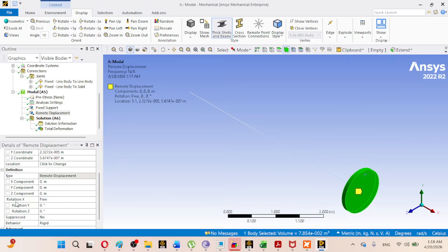So only rotation about the x-axis, which is the polar axis, should be free. For this disk the perpendicular axis is the x-axis and this is the polar axis, because rotation is not possible about y and z, since the disk contains those axes.